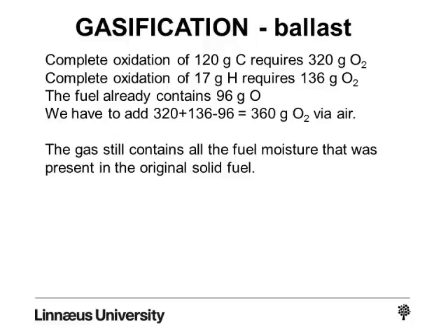Looking then at the gas quality, you will realize that this gas still contains all the fuel moisture that was present in the original solid fuel. Certainly, that moisture is now in the form of water vapor, but it is still there. And that water vapor is a thermal ballast to the gas. So is also the nitrogen from the air that we added, the gasification air that we added to get in the about 280 grams of oxygen.